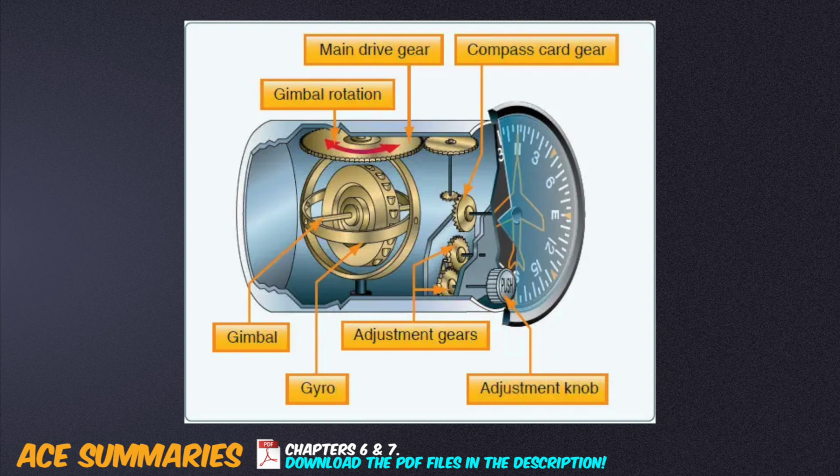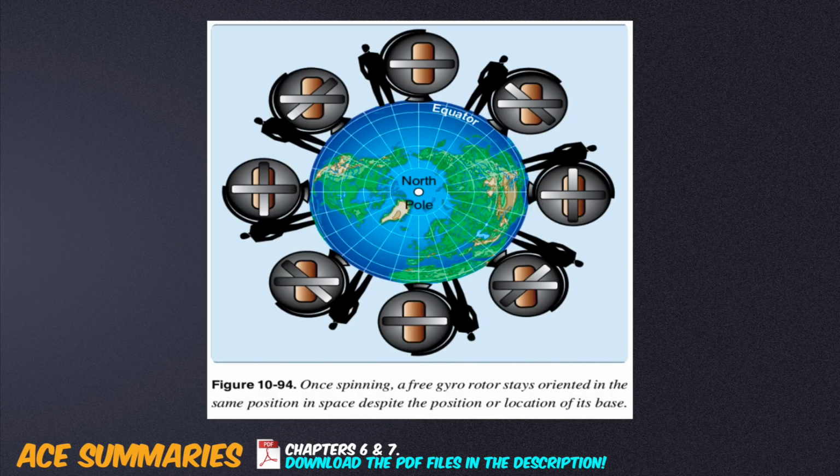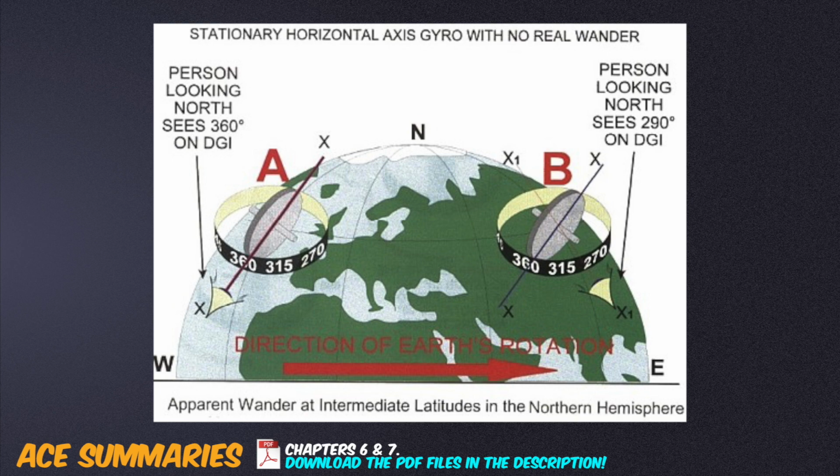A gyroscope can have up to 3 planes of freedom, each of these represented by an axis and a gimbal. A gyroscope's rigidity is a factor of the vacuum or the electric force driving it. Poor rigidity leads to gyroscopic wander, which is a movement of the spin axis away from its fixed position. This can lead to an inaccurate instrument reading. Apparent wander is a different phenomenon, and it is caused by the rotation of the Earth. Apparent wander is inescapable. To correct for apparent wander, gyroscopic instruments must be recalibrated every 15 minutes or so, or a correction must be applied with a latitude nut.